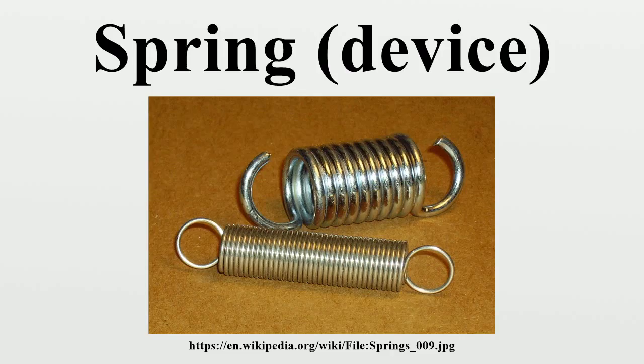Tension or extension springs are designed to become longer under load. Their turns are normally touching in the unloaded position, and they have a hook, eye or some other means of attachment at each end. Hairspring or balance spring, a delicate spiral torsion spring used in watches, galvanometers, and places where electricity must be carried to partially rotating devices such as steering wheels without hindering the rotation.